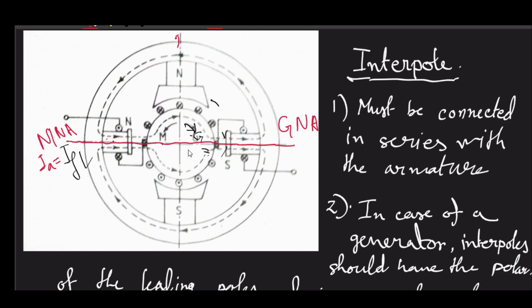But in case you want to reverse your motor speed, then in addition to armature inductance voltage, you need to counterbalance that too. Here, when you introduce the interpole, you have to counterbalance that also. So you have to be very calculative. Although this is a design issue, you will get to know more about it in your next-to-next semester, when there will be a dedicated course on electrical machine design.